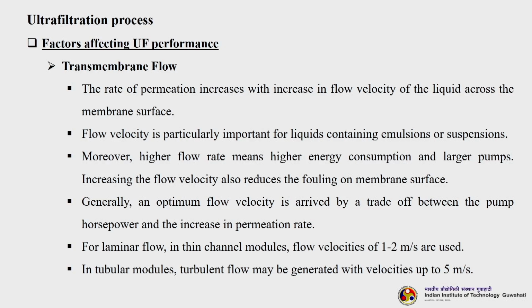There are different types of factors that affect ultrafiltration performance. The first and foremost is of course your membrane: its pore size, the membrane material and its properties. The next is the solute that I am going to separate: solute shape, size, diameter, and its properties, like whether it is charged or what type of charge it is carrying. All these things play a very important role. Now, apart from the solute and membrane, there are other factors that play a significant role in ultrafiltration performance, which we are going to discuss.